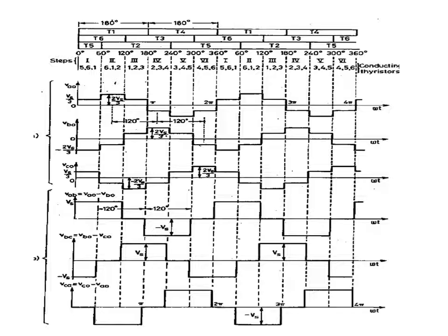Whereas thyristor T5 from the upper group starts conducting 240-degree after T1. After T5 conducts for 180-degree, T2 conducts for next 180-degree, T5 for next 180-degree and so on. In this manner, the pattern of firing the 6 SCRs is identified.